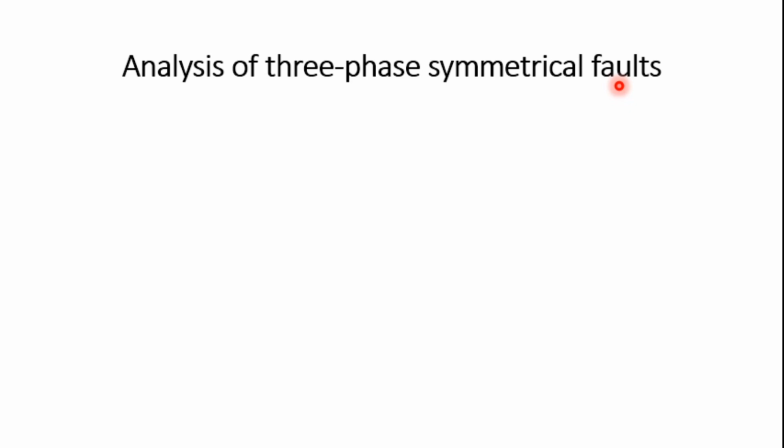The fault analysis has to be performed separately for the subtransient, transient and steady state conditions of the fault, because we know that the reactance and the internal EMF of the synchronous machine will be different in each state.